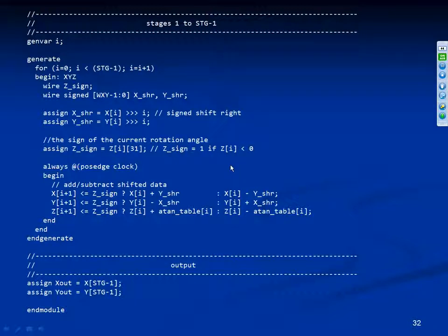I've seen some of the CORDICs that are used in like QSR1 and so on. Some of these actually have added or subtracted the virtual equivalent of a half in the low order bit to do rounding. Yes. What if you don't? Okay, I generated this one just so I could show you the basic principle of how this works. Now this actually works. I'm running it on my Mercury right now.